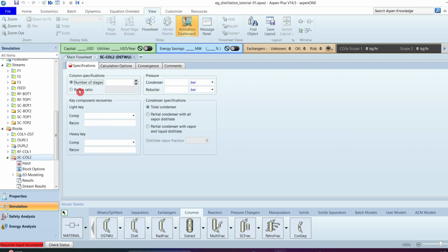Use the design specifications as in the previous practice. Let's use minus 1.3 as the reflux ratio, to have 30% more than the minimum reflux ratio calculated by Aspen Plus. Use the ethylene glycol recovery of 0.9999, that will be 99.99% recovery of ethylene glycol in the top product.